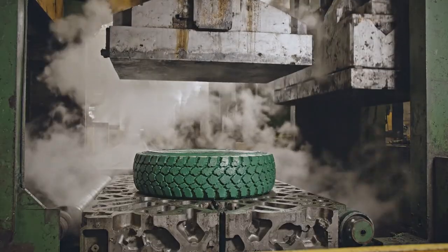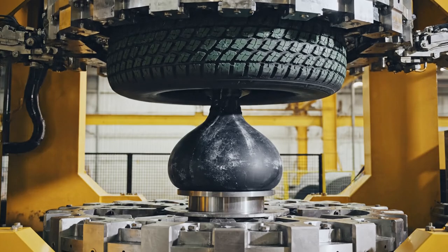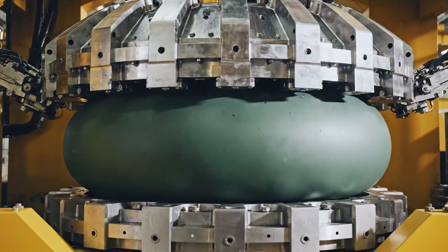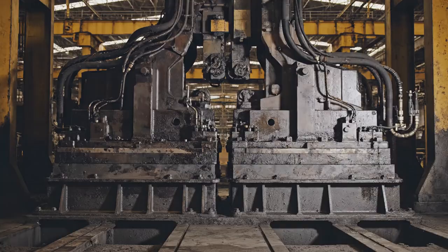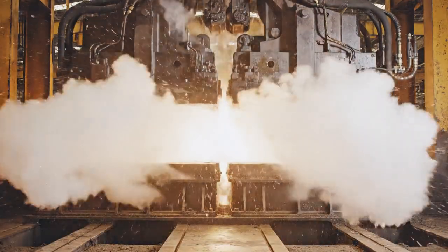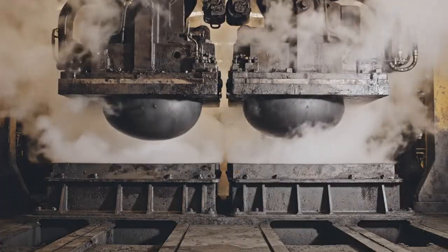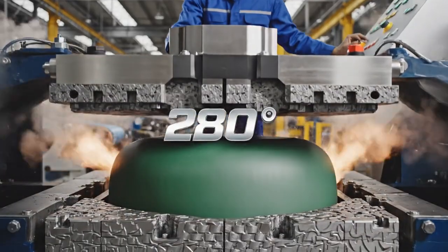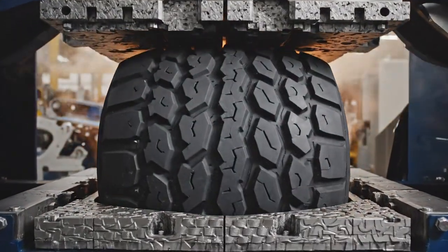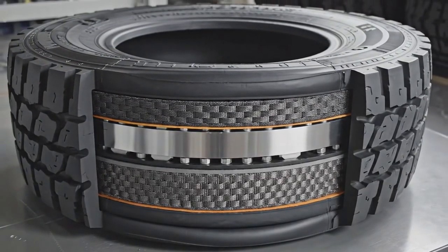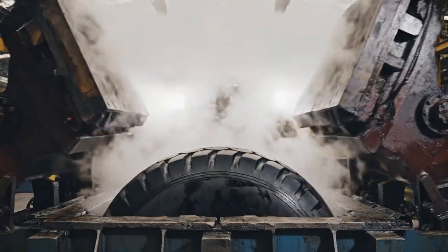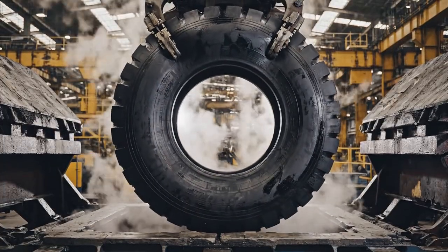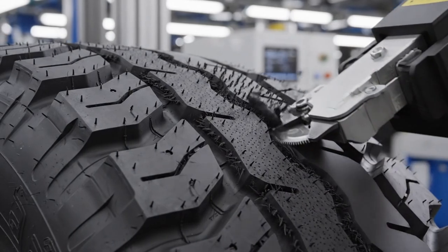A tire mold is shaped like a monstrous metal clam, which opens to reveal a large, flexible balloon called a bladder. This green tire is placed over the bladder. And as the clamshell mold closes, the bladder fills with steam and expands to shape the tire and force the blank tread rubber. During this curing process, the steam heats the green tire up to 280 degrees. Aside from the molding, the time and the hot pressurized mold cause the rubber to vulcanize, a chemical reaction that transforms it from a weak, sticky substance to one that's strong and elastic.